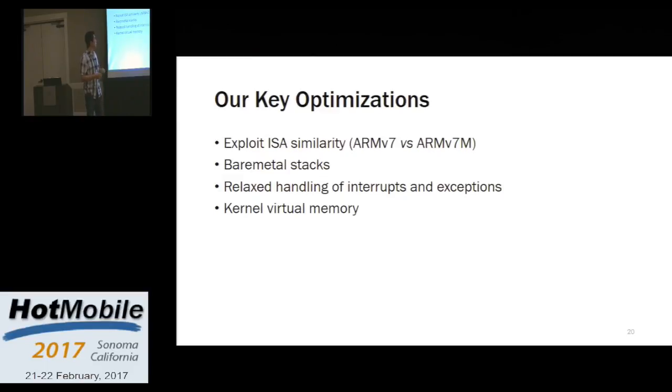For the third part, we reduce the frequency of checking the interrupt flags, because in suspend and resume, the most common exceptions or interrupts are from power transition notification completion. Therefore, we don't need to handle them immediately. And for the last part, we know that Linux kernels are mapped linearly. So whenever there's a memory access, we directly check the bound and apply an offset. And whenever there's an I/O access, we go through a software page table and do the address translation. In this way, we can get rid of the fully fledged software MMU.